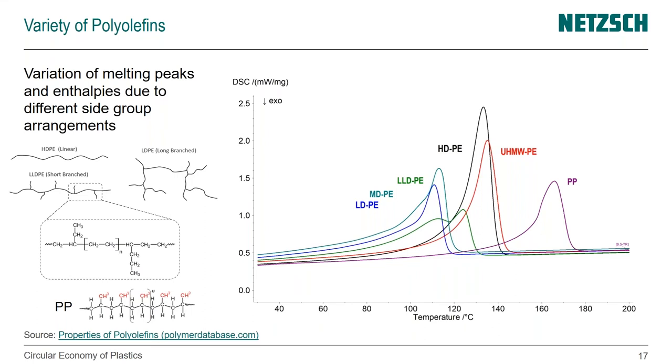The question is if aging, like UV and seawater exposure, does impact the polymer crystallinity. I think that's what that means. So melting behavior in the DSC. If the degradation really leads to chain scission and significantly lower molecular weight, then you would have a problem because your material might not appear as a PP anymore.